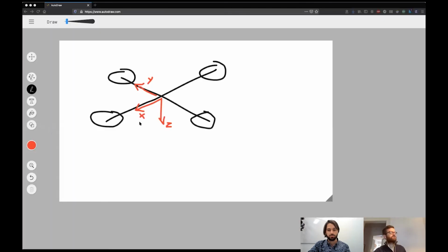All right, so usually when you have a quadrotor, we often use the NED frame, which stands for north, east, down. So this is what I drew here. We have a quadrotor with the x-axis pointing forward, the y-axis to the side, so east to the right side, and the z-axis down. This is where the NED frame convention comes from. And then the question is how we can find the allocation matrix. The definition of the allocation matrix is basically how we relate the virtual inputs to the rotor speeds.